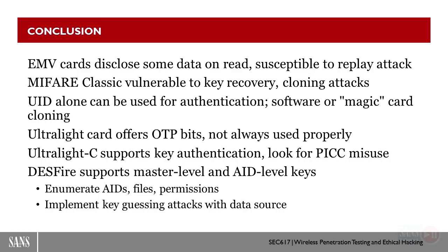We talked about MIFARE Ultralight and Ultralight C with some authentication and the one-time programming bits. And then some better security with the MIFARE DESFire line with multiple applications and some updated crypto types, in which we're left to do key guessing attacks and true brute force to interact with to be able to potentially have any security issues with those cards.